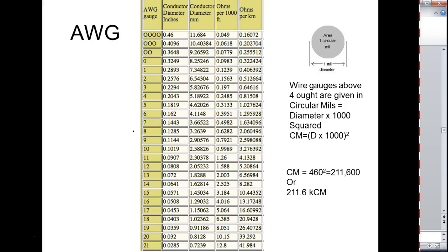And of course, we wouldn't be able to measure that with a standard ohm meter. The lowest scale on this meter is 400 ohms. So on the 400 ohm scale, if I measured across this thing and it was only a foot long, it would measure 0 ohms. Now of course this is at a certain temperature. Unfortunately, they don't give us a temperature.